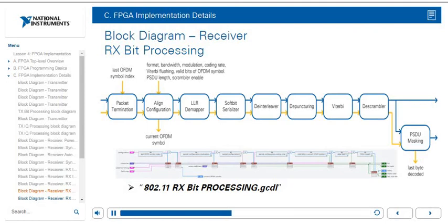The first is to align the bit processing configuration cluster from the RX PHY state machine with the start of a new OFDM symbol. The second function of the alignment configuration module is to filter non-coded fields for downstream modules. It uses the field map provided by the XIQ processing chain. The deinterleaver module reverts the BCC interleaver operations. The depuncture module converts the incoming bit stolen data sequence to bit inserted data sequence. Each bit gets a puncturing flag attached depending on whether it was transmitted or left out.